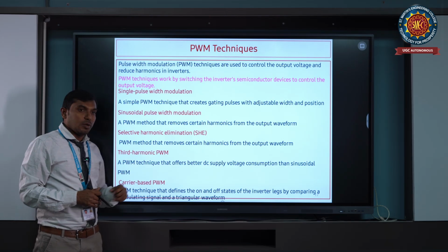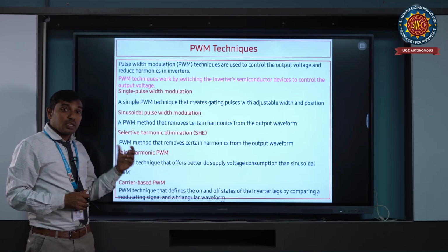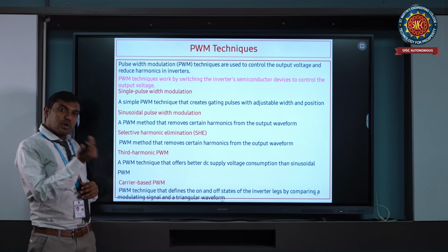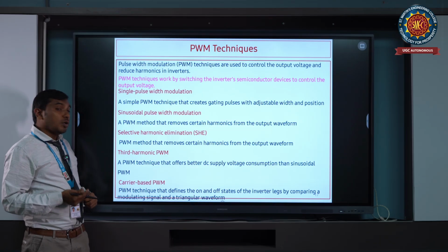And this is third harmonic PWM technique. So what is third harmonic? We can inject third harmonic into the PWM signal so that it is eliminated from the output. That technique is called third harmonic PWM technique.